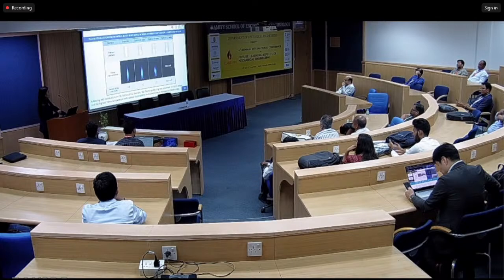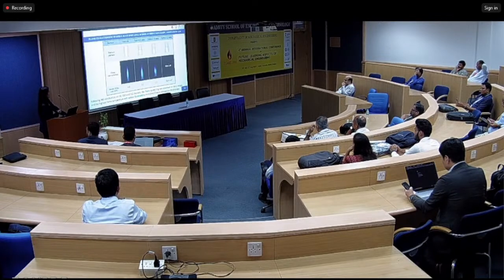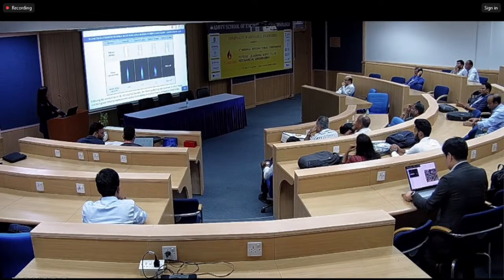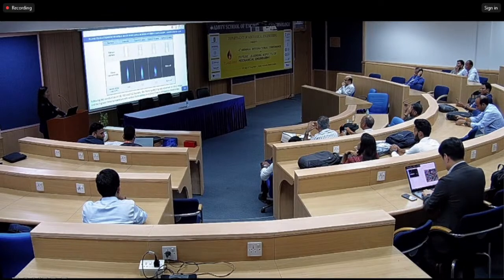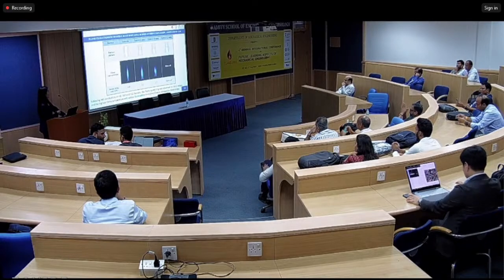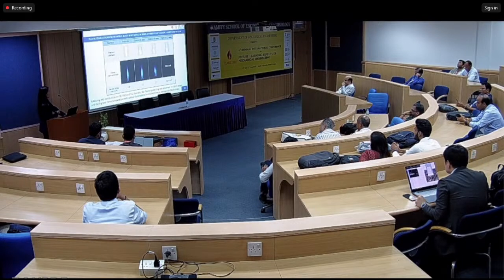In the case of the development S8, 10, and 12, we obtain a blow off or quenching flame at S12. So we cannot ignite the flame from the S12. In the case of S8 and 10, the size of the bluff body increases when the S increases, right? And this is the kilowatt at which we can obtain ignition of the flame, only 3.2 and 2.2. So we can obtain the ignited flame around this kilowatt, maybe less than the reference firing rate.